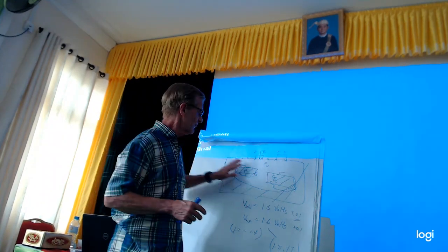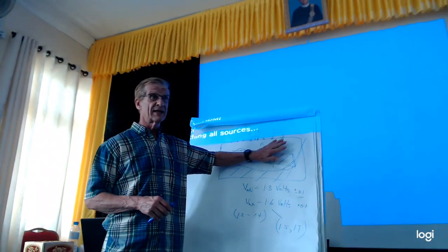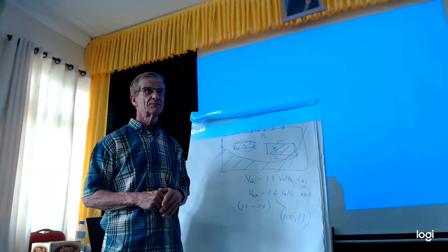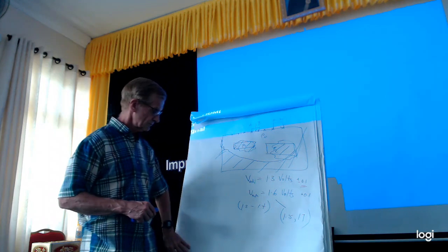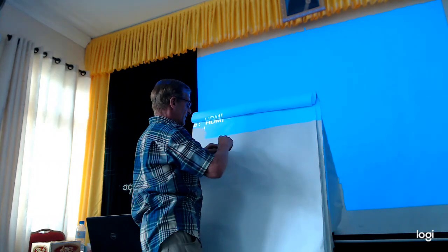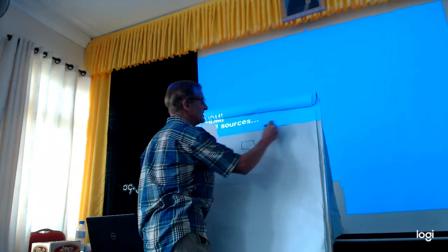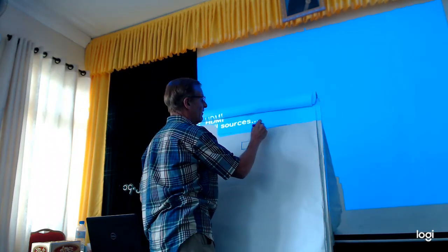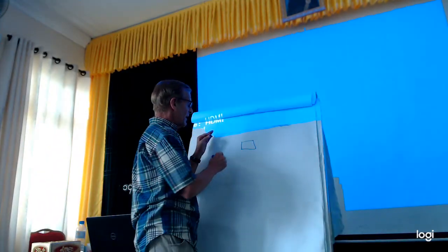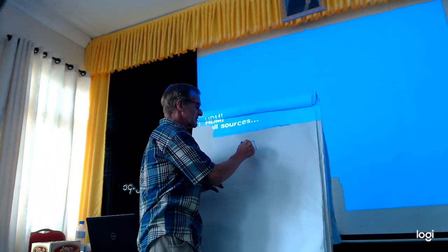So how do I account for that? Well, maybe I should try to look at a forward modeling and see how much difference it makes if I put a body at depth. Yeah, you could do this even with a very simple model. So let's suppose I have a uniform half space, and now I put my array on top, Schlumberger Wenner, whatever, and then I attempt to see if I can find this block.